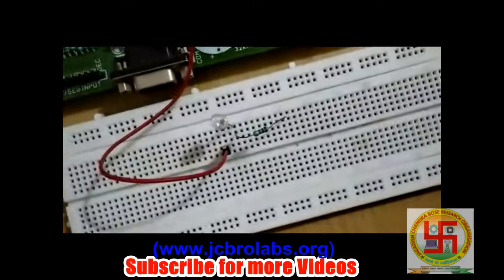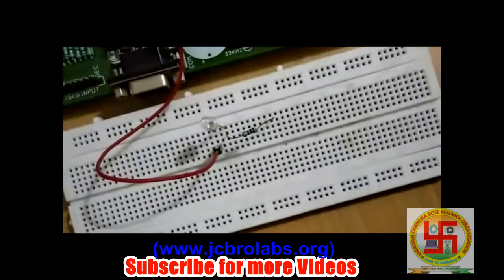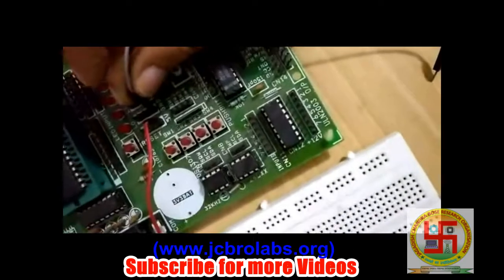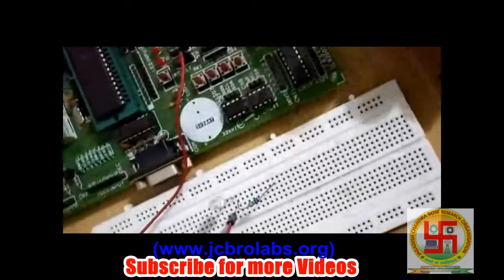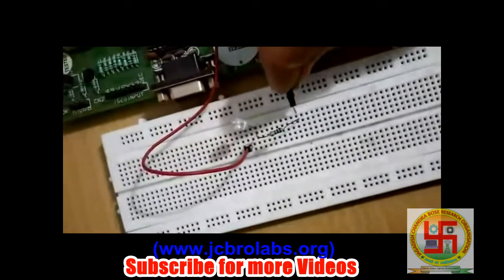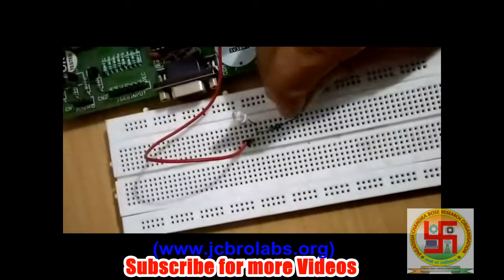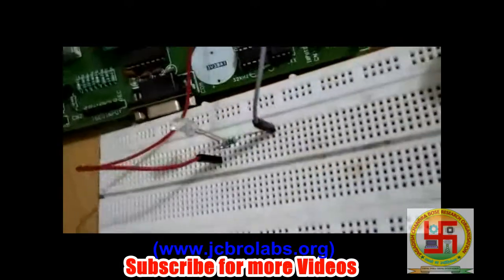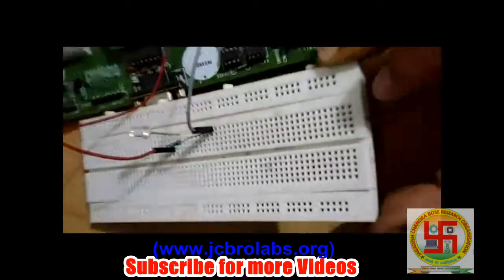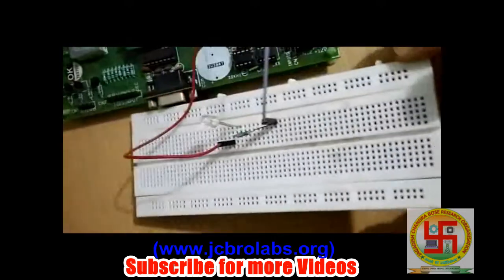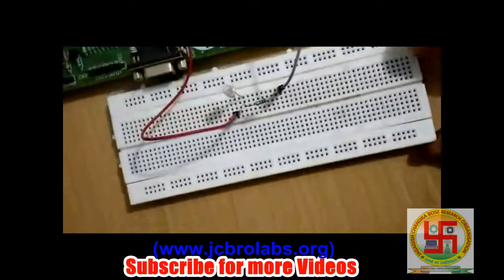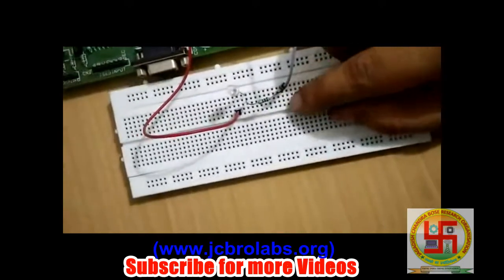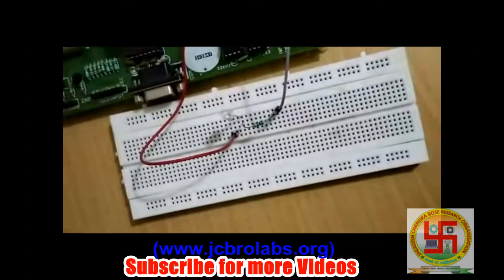And now we will connect the ground. Let's connect ground here, and it goes to the resistance leg, in the same line where the resistance's other leg is. So it goes like this. If you can see, these are connected. The connections which need to be made should be put in the same vertical line. So this is how our circuit is complete.